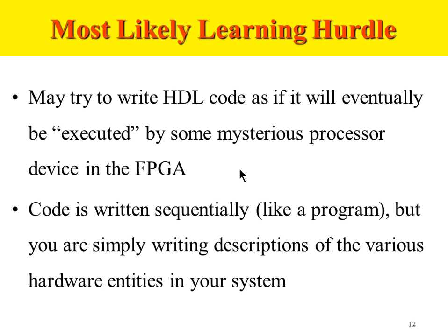On a microcontroller, the entry is in C language, where the C program will be executed sequentially. On an FPGA, the entry is in Verilog or VHDL design languages, and it will work in parallel based on your design. Because hardware design has to have parallel logic. That is how hardware works. It doesn't work sequentially, it has to work in parallel. FPGAs support that. So when you describe designs, I will always repeat that I don't program my FPGA, I describe my design on the FPGA. When you do that, you have to keep this in mind.